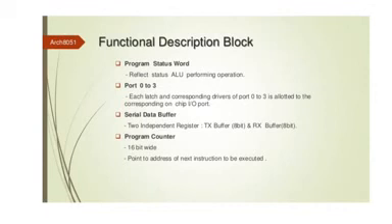Parity flag tells you, depending on the number of ones in the result, if you have an odd number of ones, the parity flag will be set to 1. Whenever your result contains an even number of ones, the flag is in the reset condition.